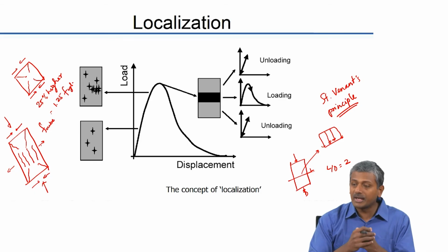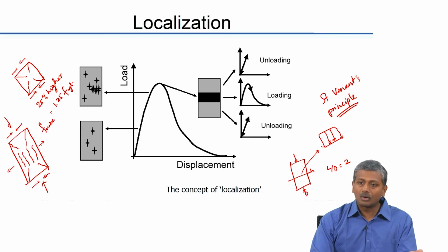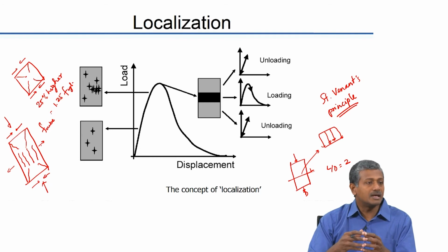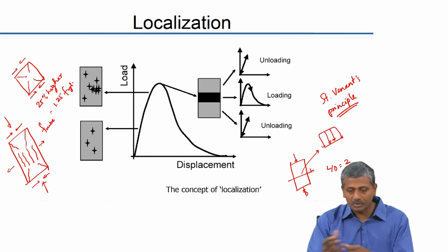So in that case, you can actually get strengths from a regular concrete of 30-40 megapascal as much as 300 to 400 megapascals, right. When you test under triaxial conditions, your concrete strength will get severely enhanced because of that, and we talk about that also later.